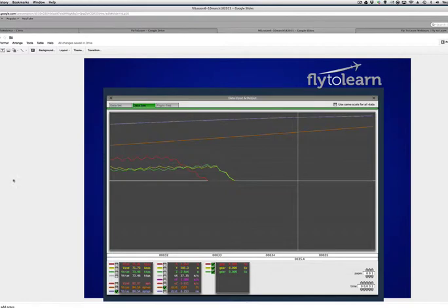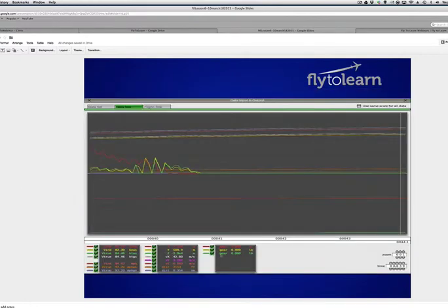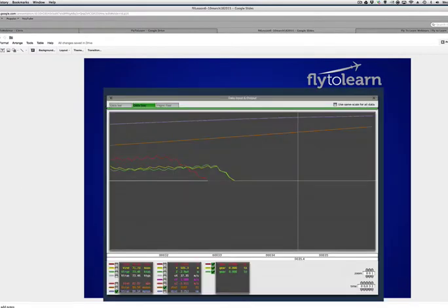When you're graphing this, remember they have all these check marked. You can uncheck most of these and just use what you need. You need to know the landing gear, you need to know distance traveled, and you need to know your airspeed. That's usually the things we're measuring. Right at this point here, you can see the red, the yellow, green. That's the landing gear. They all went to 0 at this point right there. And once they go to 0, and in fact over here where the white line is, you can see it's all 0, 0, 0. All right? And that's what we define as takeoff.